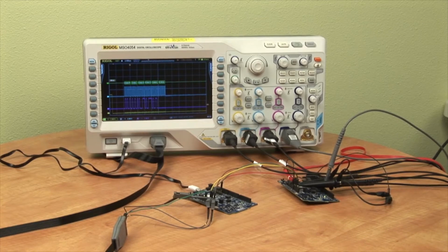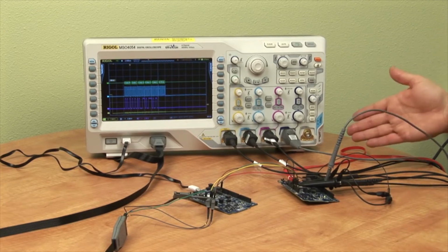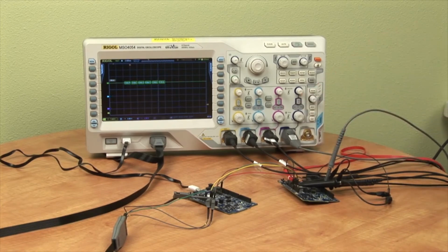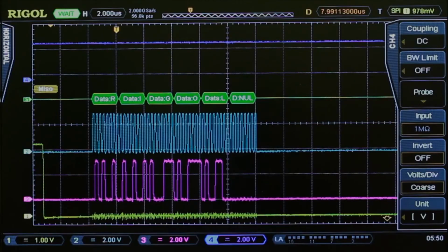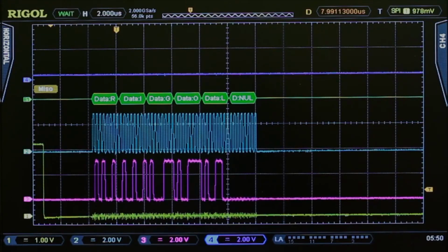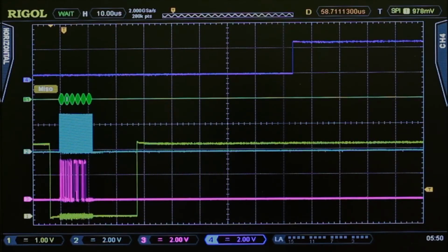The last thing we want to look at today on your SPI bus is some timing and latency issues. How your code is implemented has a big effect on latency and timing, and how quickly the serial data can be acknowledged. So we've done a couple things. First, we've added another probe here. We're going to turn this channel on, and this is really tied to an acknowledge bit on the slave. So if we zoom in time here, we can see the acknowledge bit happens a fixed time after the transmission. So really, whenever the SPI bus is communicated, it's received in about the same amount of time.